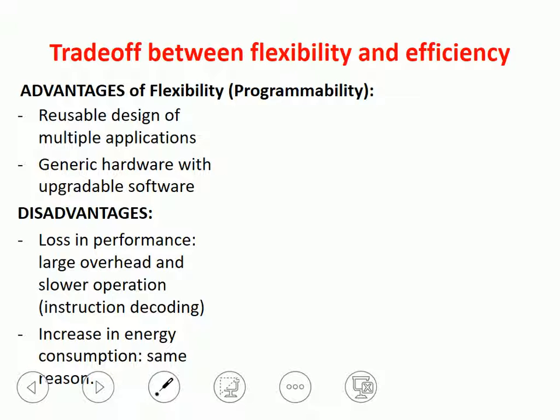The trade-off is pretty clear. On the one hand, flexibility has two big advantages. The first is that, of course, we can reuse the design for multiple applications. If we have a flexible block, we can reprogram it and use it in another piece of hardware, using an identical piece of hardware with a different configuration or with a different program, and we do not need to redesign it and to pass all the fabrication hurdles. And then another advantage of flexibility, of course, is the possibility to upgrade the hardware by only changing the software. So if we need to change the operation of a block, we just need to reconfigure it or to reprogram it. Okay, these advantages are pretty clear and apparent.